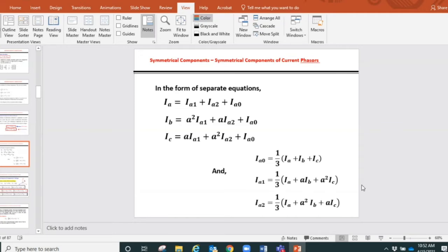Sometimes we leave the star ungrounded, sometimes we ground that star with some resistance, sometimes directly, sometimes through another transformer. We do a lot. Those conditions will come into the scenario when we do the positive sequence impedance, negative sequence impedance, and zero sequence impedance. They are not as simple as the way we arrived at the equations of currents and voltages for the sequence components. They are a little bit complicated, but we'll learn step by step.